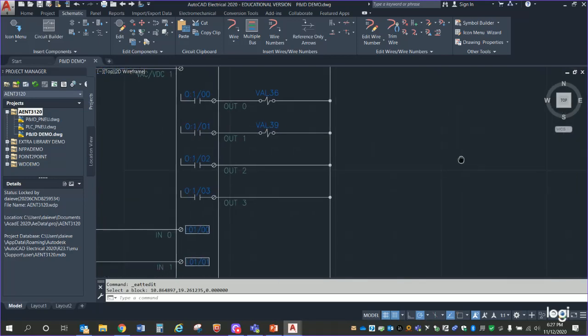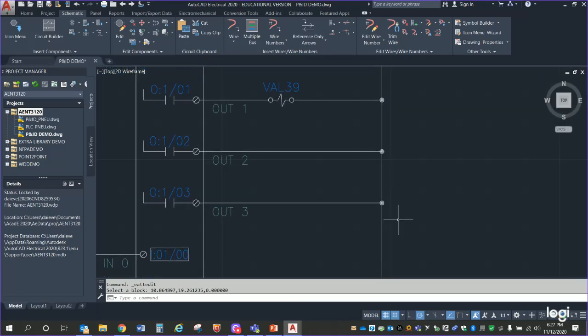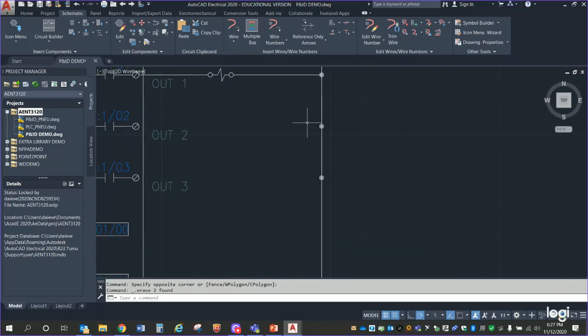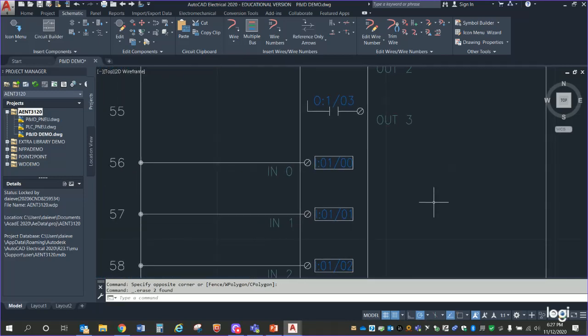Those seem pretty simple. I'm going to get rid of these other 2 outputs. I only have 2 control valves that I'm running right now, so I'm going to make sure those other 2 outputs are not wired up directly to the rail and doing nothing. And also, another little pet peeve of mine, notice the little dots. I'm going to get rid of those little dots. Why? Unnecessary. They're not connections anymore, are they? I don't want them on there. They just kind of clutter up the drawing.